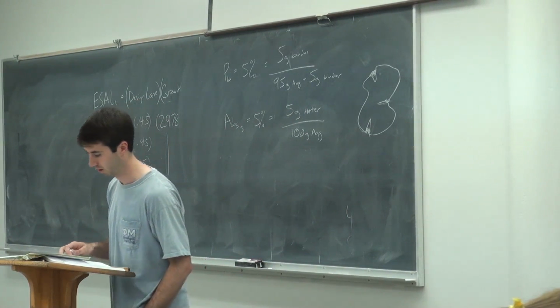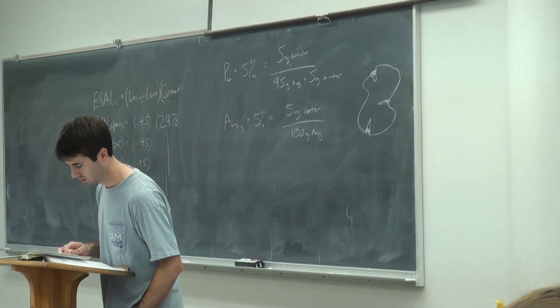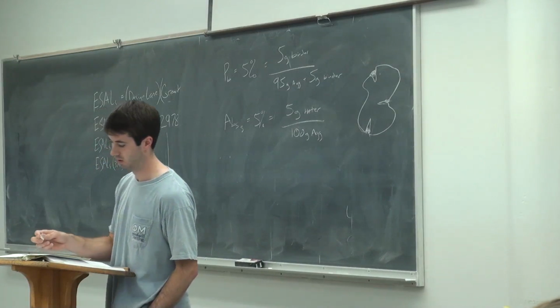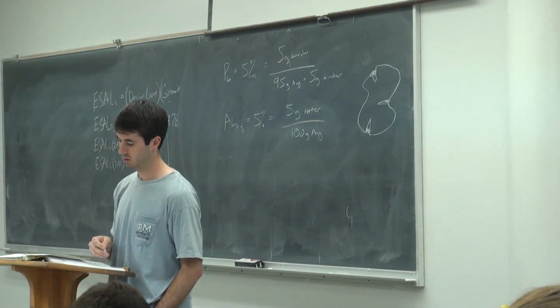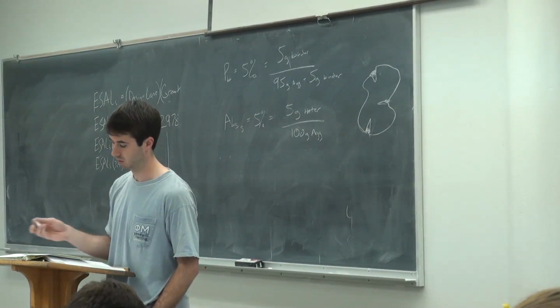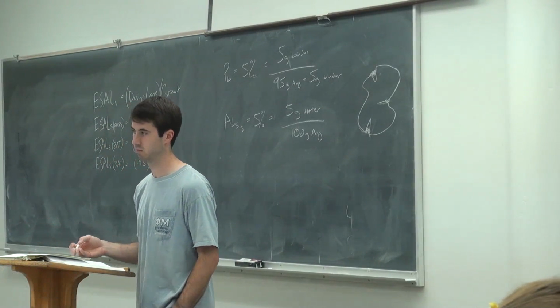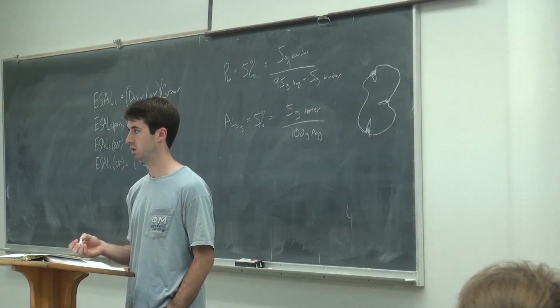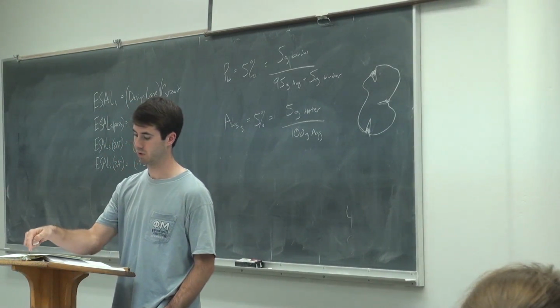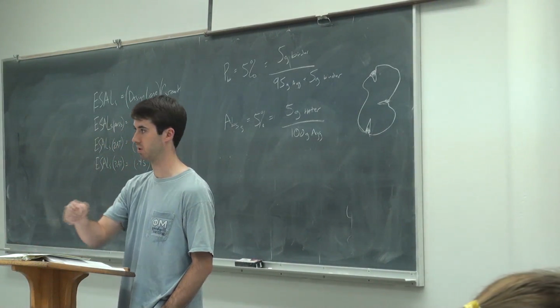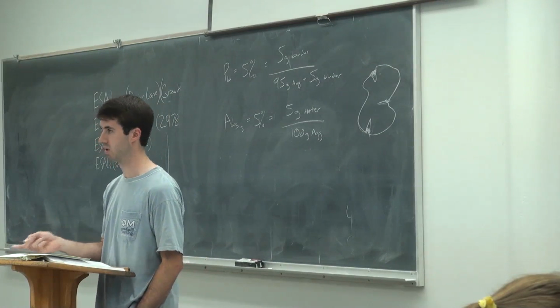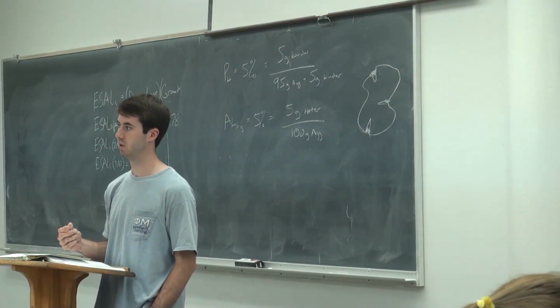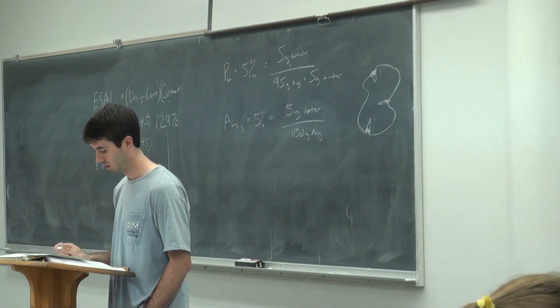That's because VFA, if you look at the phase diagram, is voids filled with asphalt, and most of the voids themselves are asphalt. So it's not out of the total, it's basically VFA as a percentage of VMA. So that means 65% of the 17% voids is asphalt.